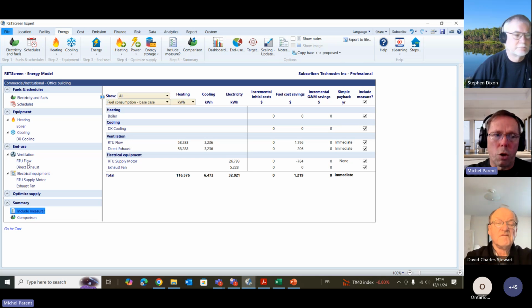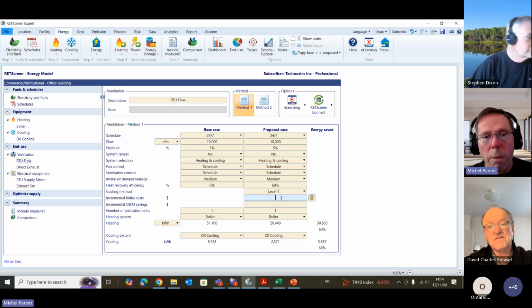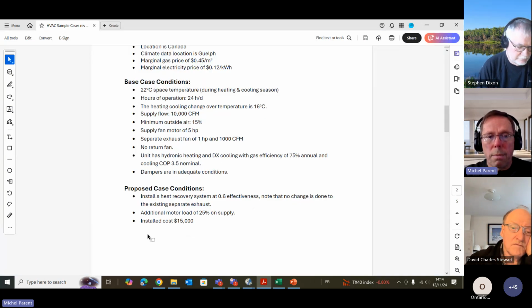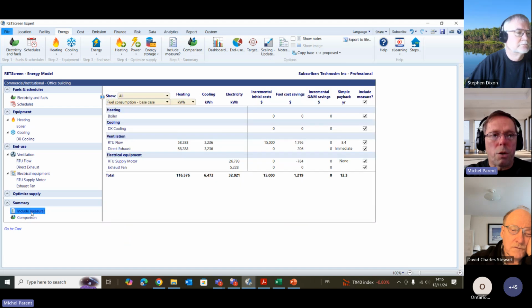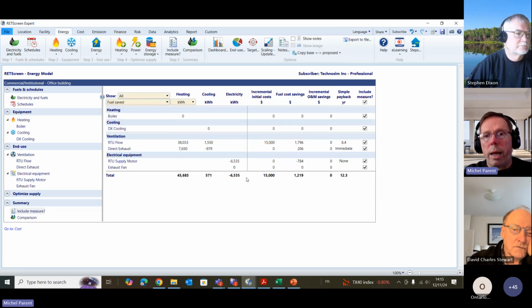So now if I go back to my include measure, oh, I did not enter the cost. I'm sorry, guys. I'm going to go back to the RTU flow, so we see what is the payback. And you can look at way more than payback in RETScreen, by the way. I'm showing you payback because it's simple to look at right now, but we can look at way more than that. So I'm going to say it's $15,000. Now I can go into the include measure, and I'm going to go in fuel saved, and we have 12.3 payback.